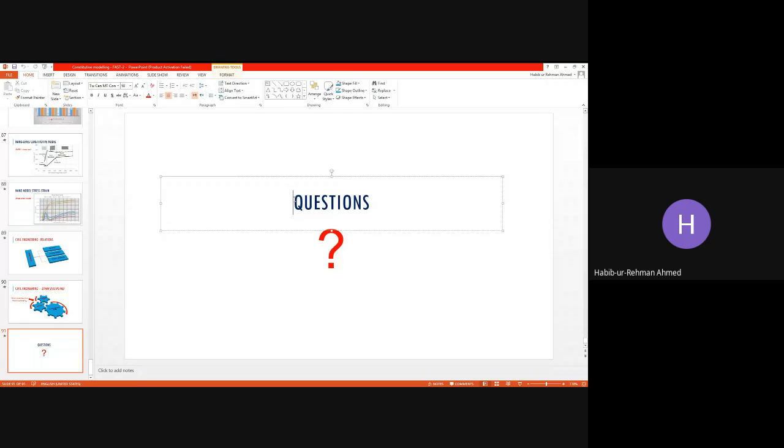Look at the behavior during triaxial tests. Look at the behavior when doing field testing. This will definitely give you a model in your mind. And if your model does not synchronize with what you are producing, then you will be alarmed. You'll say, no, it is soft clay and it is giving me results which are not making any sense. So the most important thing is you have to love the soils and rocks. You have to go and watch them, and you have to incorporate their feel in your minds. Only then will you be an excellent geotechnical engineer.